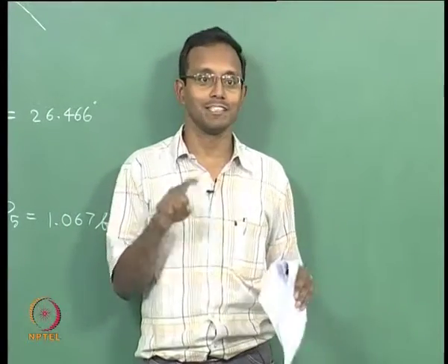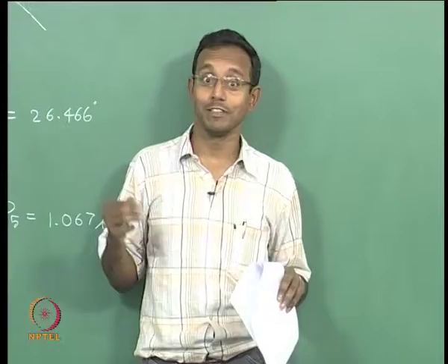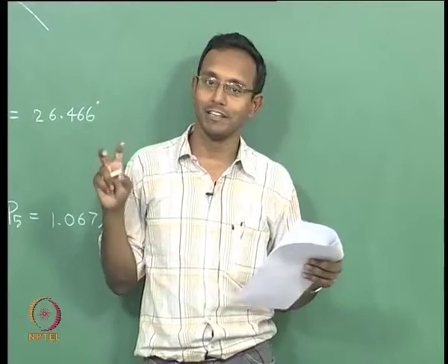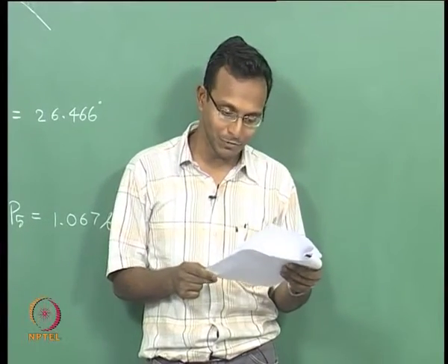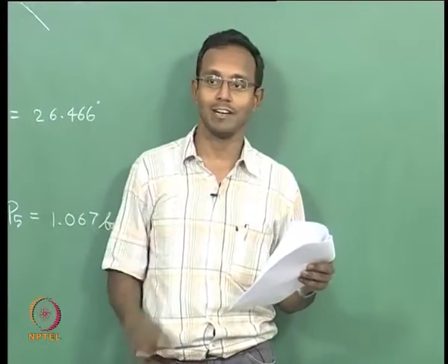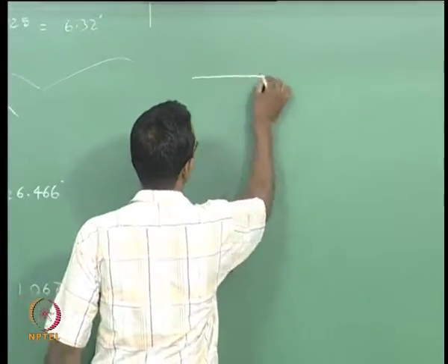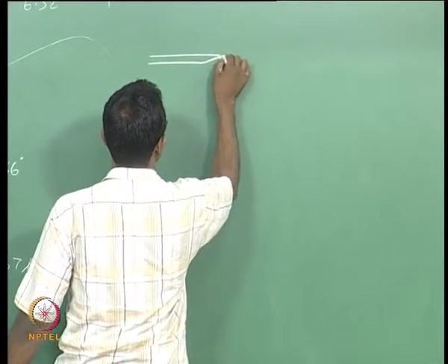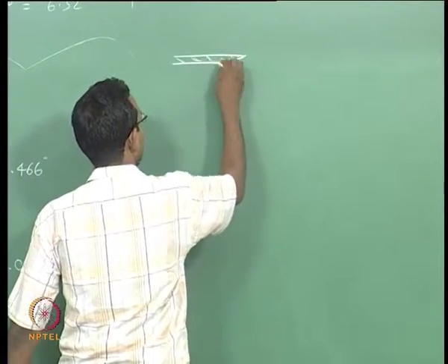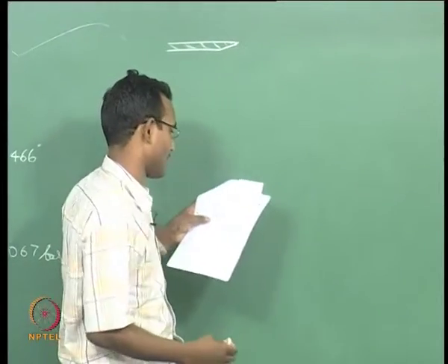which will eventually come down to equal velocity distribution everywhere. If there is any velocity gradient, there is some vorticity at that place. That is what we are trying to achieve finally, that is what it will end up with as a final situation. That is the job of viscosity in nature. It is diffusing velocity differences, or momentum differences, among fluid elements of different layers. Ideally I should not be teaching this here, it is a fluid mechanics course. I am supposed to be teaching only compressible flows, but I will give you this so that you have that background when I start talking about supersonic compressible shear layers.